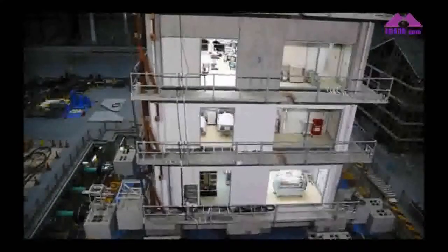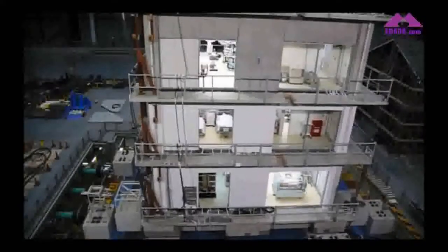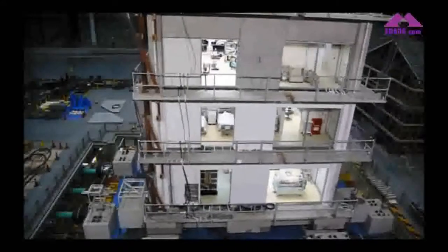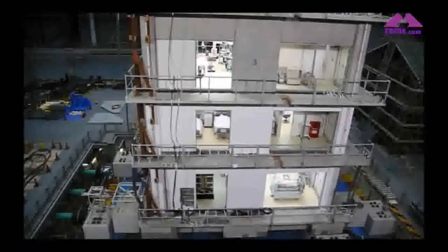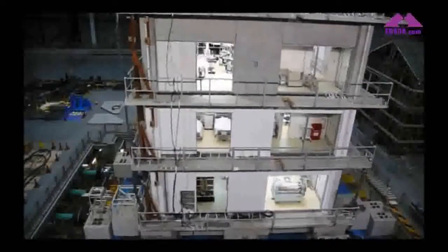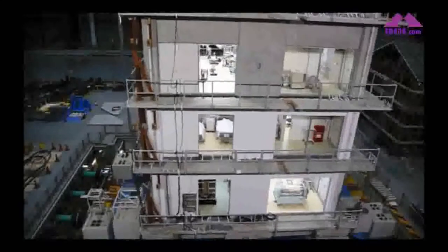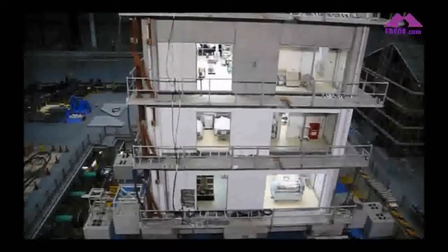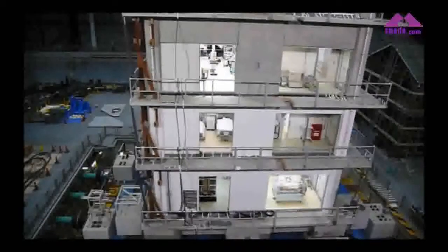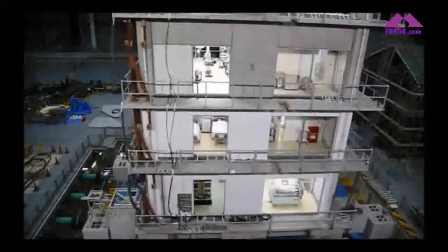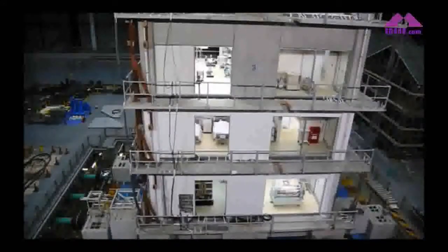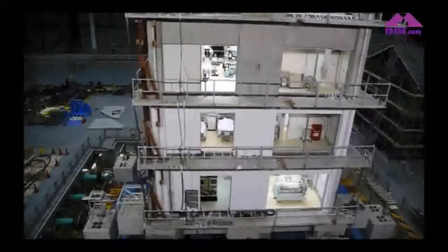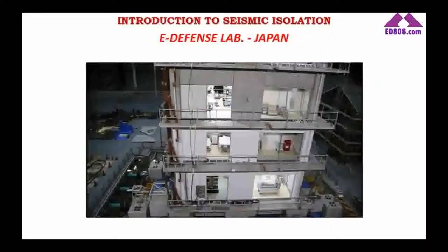What we see, normally if it was a conventional building, we would see damage on the structural members, even in the non-structural members. But what we see only is that the doors, sliding doors, opening and closing, some unfixed furniture with wheels, they move in the room. Some suspended elements move also, but this is not in such a high magnitude earthquake. This is something acceptable. We do not see any damage in our building, nor